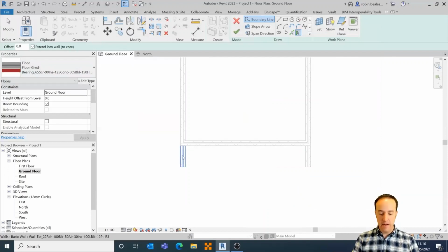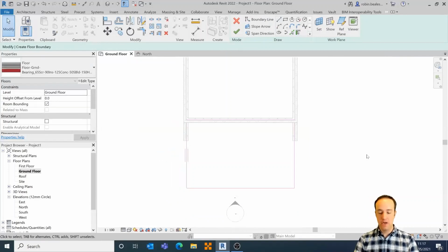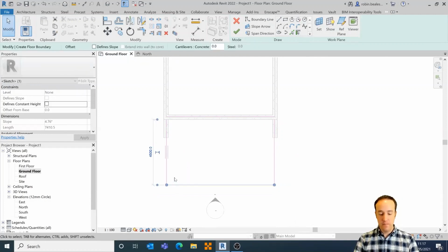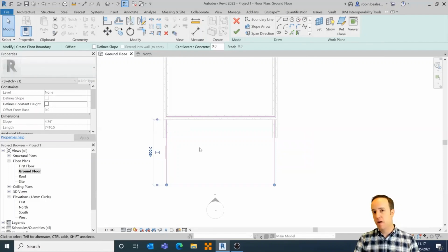And again, I'm going to pick just these 3 walls, join them up with a line, using all the standard tracking and snapping that you would be used to inside of something like AutoCAD, and place down a dimension to control that I want that to be 4.5 meters. Now, the dimensions are what we call temporary dimensions in AutoCAD, in Revit, in that they're only showing when we select what they are related to.